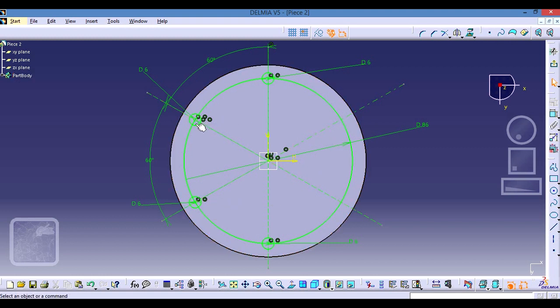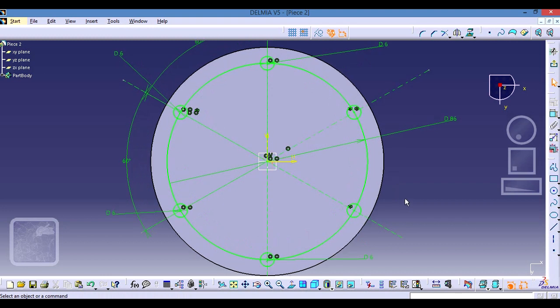I will add once again by using mirror, clicking here. I will click here to make the reference. I want it here, and here I have my other circle, and I will use mirror again to copy this one. The reference is this line because I want the other circle, the copy, I want it down, and that's it. What I need to do now is to erase all the settings of this figure, all the lines that are not far from the original design.